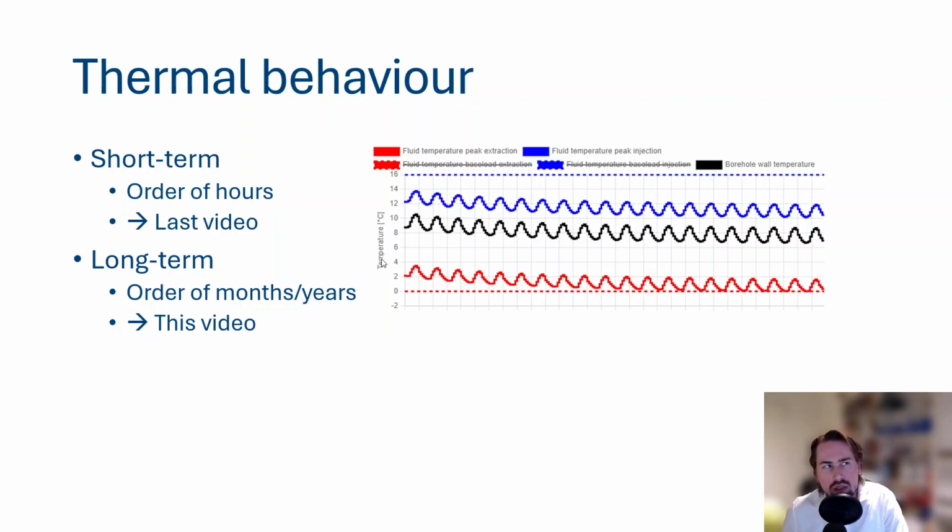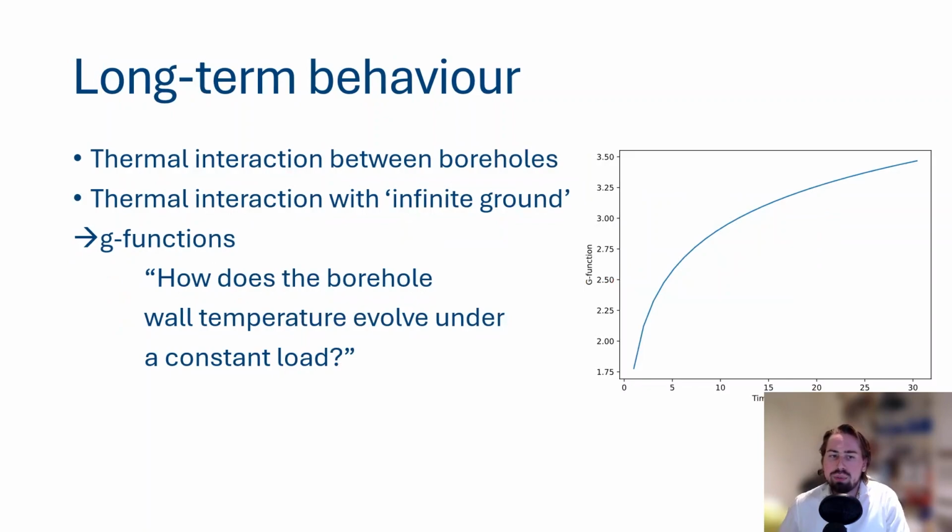So trying to answer the question how the borefield evolves thermally over time, it's solving a three-dimensional transient heat diffusion equation, which is extremely complicated. Because you have the thermal interaction between the different boreholes, which is important, and also every borehole is also interacting with the infinite ground. So the heat exchange does not stop at the boundaries of your project. No, it continues in the ground, and this interaction is also really important.